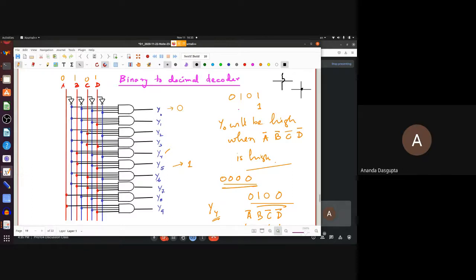Okay, this convention is not completely universal, but almost always when you want to show a connection in a digital circuit, the rule is you have to explicitly show the connection. Okay, that's universal. In all digital circuits, you show connections by showing a blob. Not necessarily a blob which is this big or drawn in color. And most often it will not be drawn in color. Definitely not in multicolor, the way we have drawn it. But the blobs are essentially to show that there are connections.